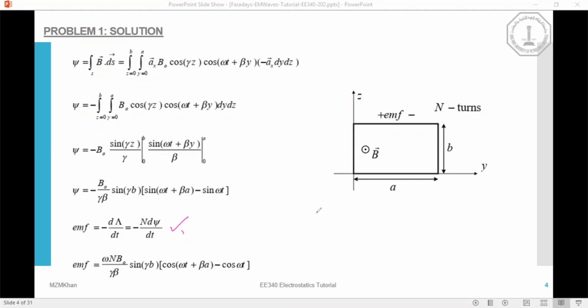Okay, yeah, other way around, yes. For example, for your transformer EMF, which I told you, minus integral over surface dou B bar over dou t dot ds, or for your motional EMF, which is equal to closed line integral E bar dot dl, or closed line integral U bar cross B bar dot dl. Yes, in some cases, applying this becomes very difficult and this becomes very easy.